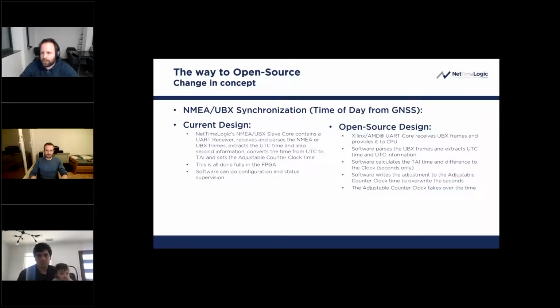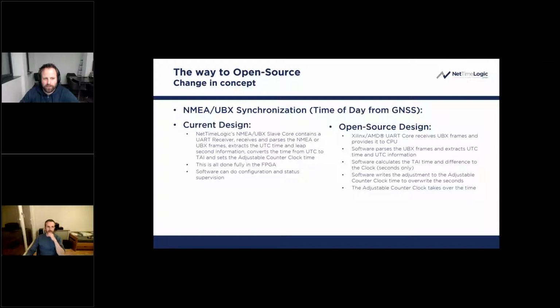It extracts UTC time and leap second information, and takes those two things to convert UTC to TAI, and in the end sets the adjustable clock in the design to the right seconds. This way we get the time of day at a granularity of seconds, and this is all done in the FPGA directly, and the software can just do some configuration and status supervision. For the open source design, we planned a different approach.